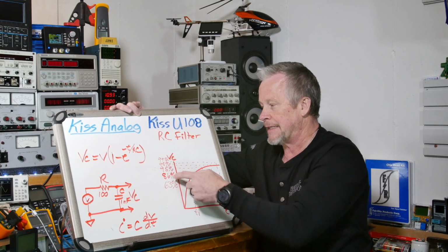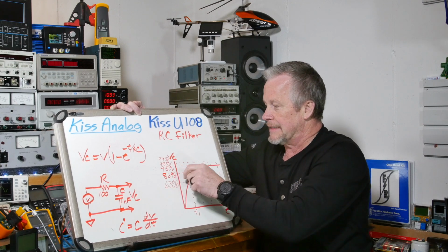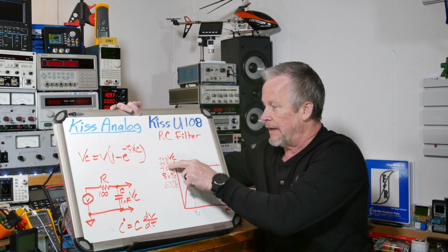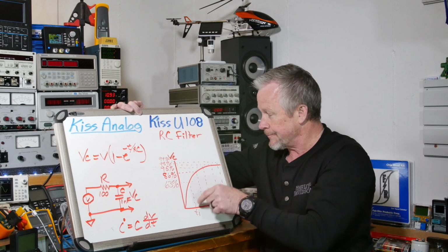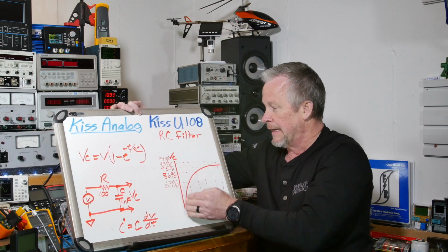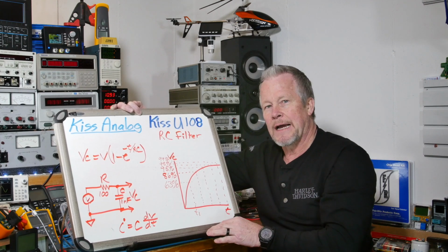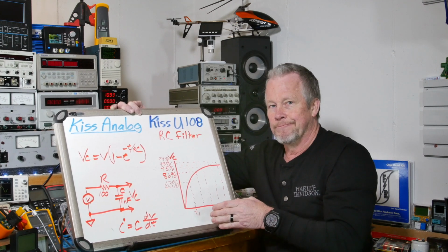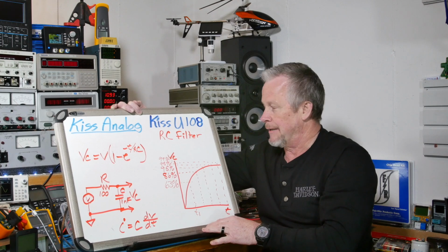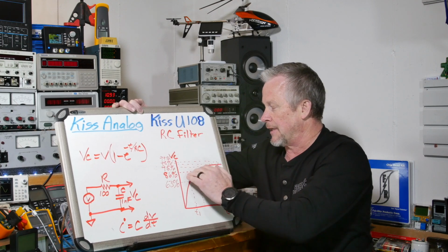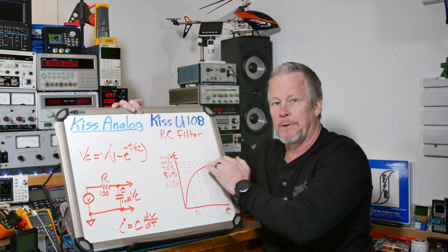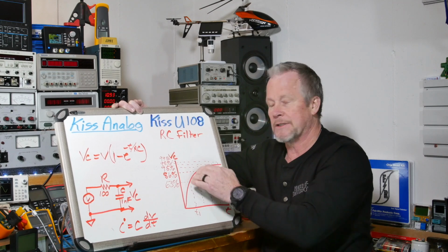And second time constant, 86%. And then you can see how they get crunched: 95, 98, 99. So it flattens out after about the second time constant. So really, in the first 2 time constants, you're getting pretty charged up. And that also means the current going to this part is a lot less than it was through this first part.